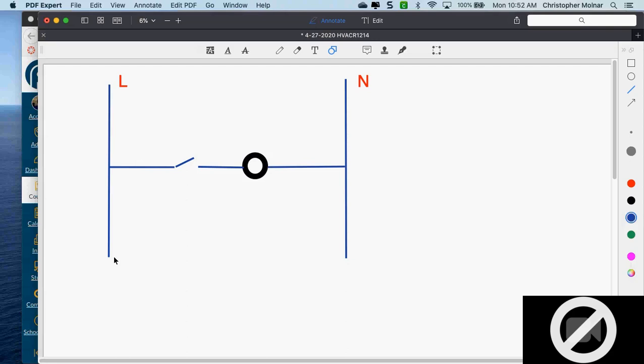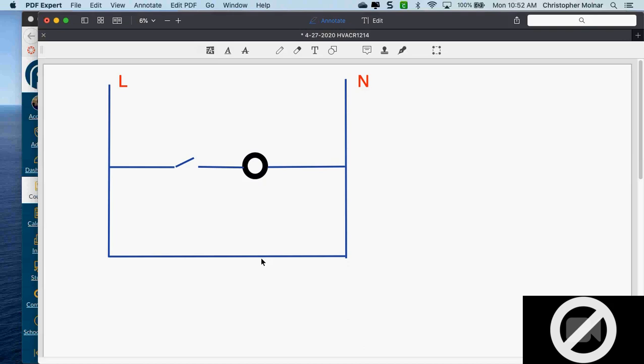The other thing that I saw some people doing, especially on the hand-drawn schematics, and overall the hand-drawn schematics are looking really nice, but what I saw a couple people do, and I've been seeing this for years, so this isn't anything new, is that you're taking something that has a rectangular shape and you're drawing around it to get the base of your schematic. I know this is by accident. What's wrong with this circuit? Basically the same thing as before. You're going to have a direct short circuit, so this schematic would not work.